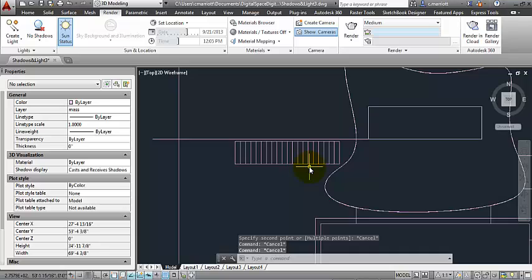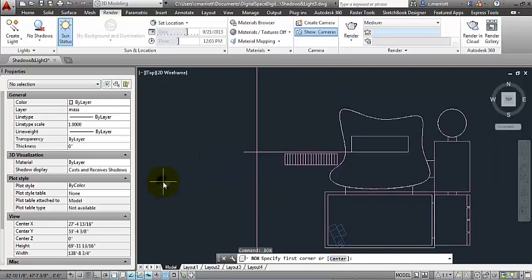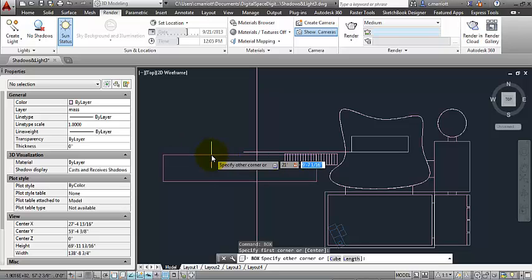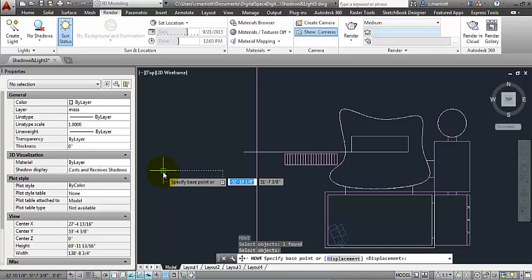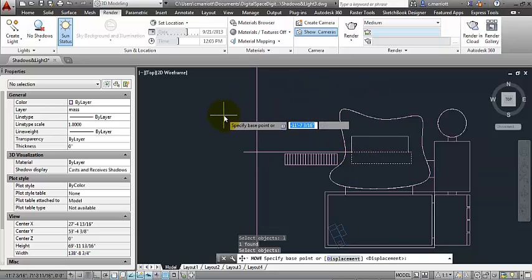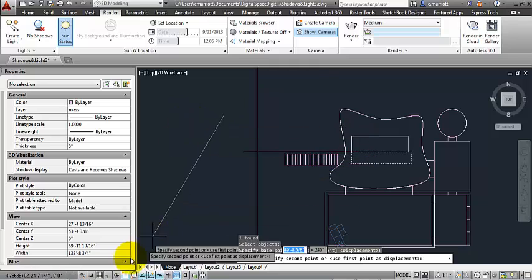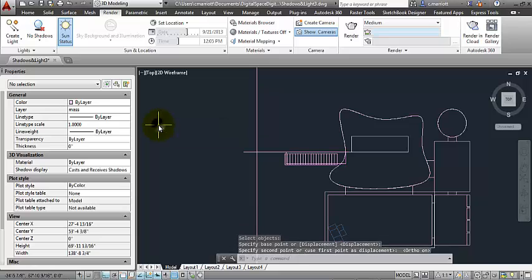I'll make it perhaps 21 feet, this hollow space box, and I'll construct it over here on the side. 21 feet, comma, 4 feet, comma, and we'll make it extra tall. So here I have a box, and now what I can do is move this box using a series of reference points, and I'll turn my ortho back on, slide it to about here.